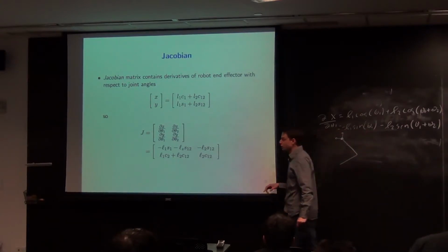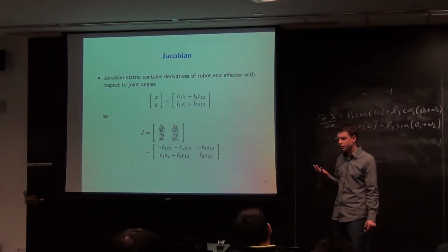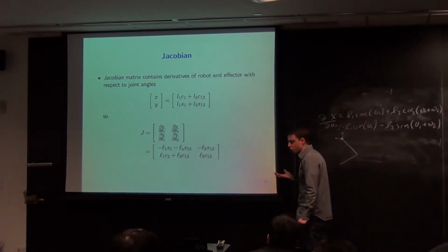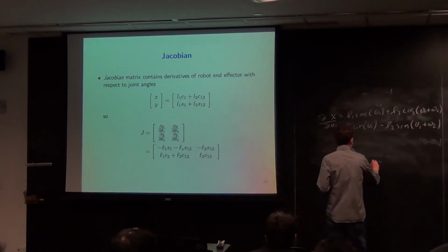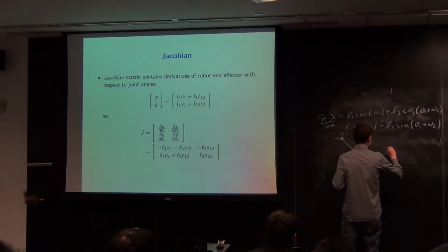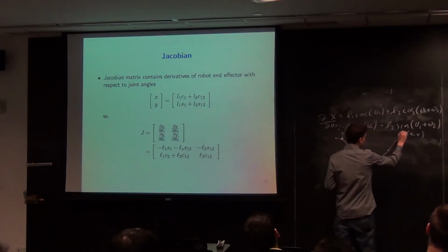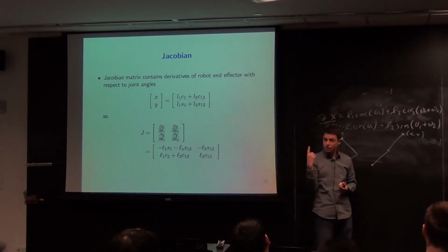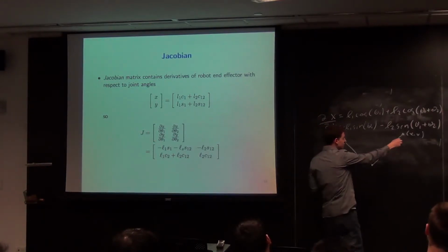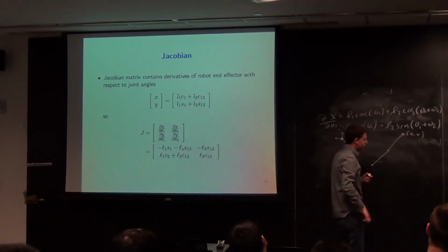And one thing you can use this for, amongst many other things, is a smooth version of the cases we talked about before, where you may sometimes have one solution, or you may have a lot of solutions to the inverse kinematics problem. What we found is that by pure inverse kinematics, if you pick a point x, y that's right on the boundary of radius L1 plus L2, that will have exactly one solution, whereas if you move even a tiny little bit in, it'll have two solutions, right? Because you could now either be crooked a little bit this way or a little bit that way.